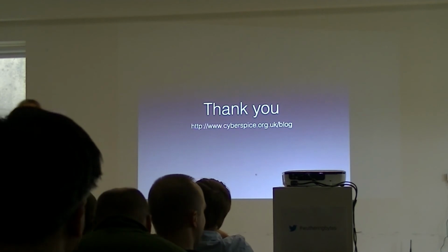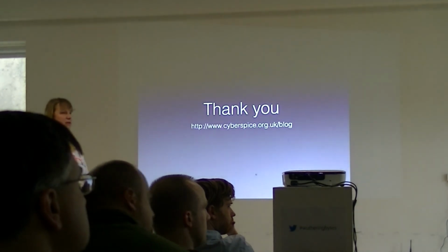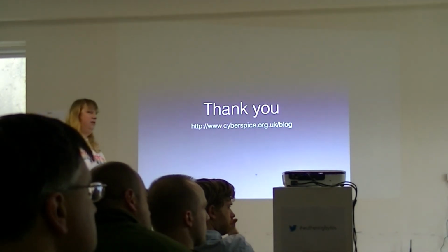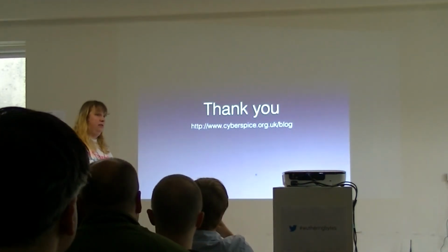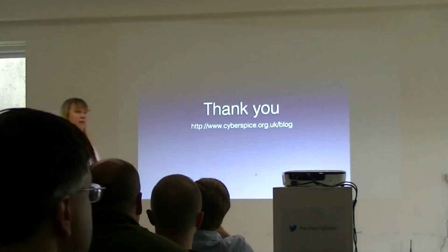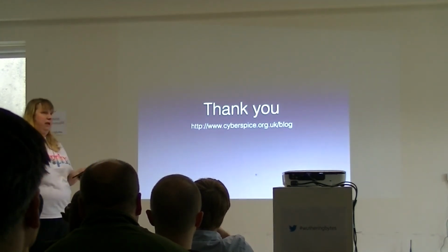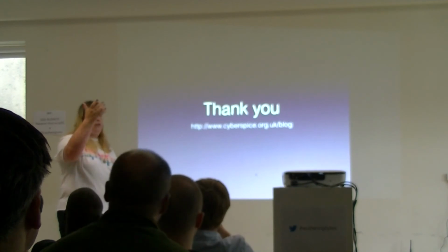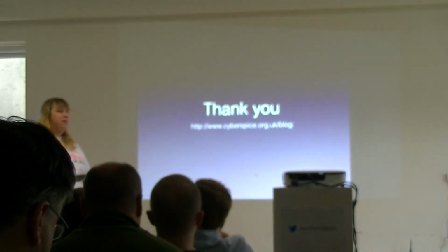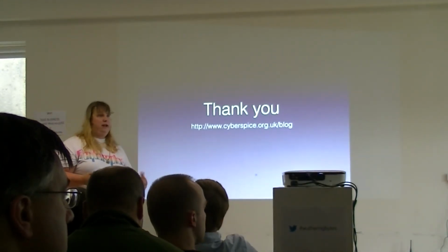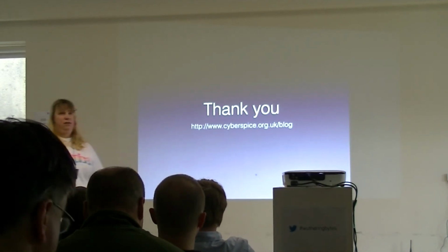Thank you very much. I've just got a question about measuring analog values. So it says it measures the voltage difference across the two pins. So do you actually get, say, an 8-bit value coming out of that when you read and shift them all in? Yeah. So rather than 8 individual bits, you're getting an 8-bit value that represents the voltage difference. There's going to be limits in there. You have to look at your spec. You can't go connect one to 5 million volts and the other to, of course. But yeah, it's all relative, and you just read it. And there are 12-bit ones, there are 16-bit ones.